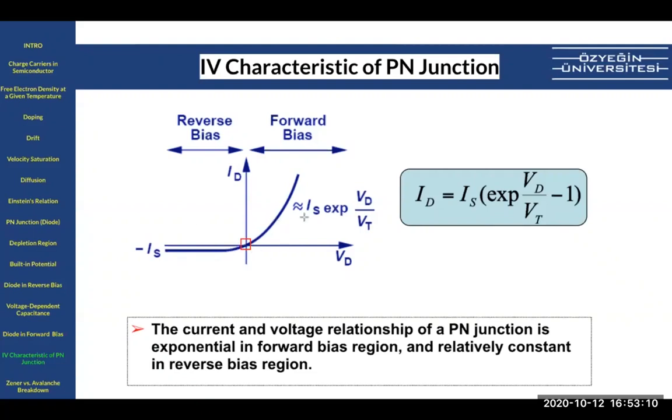But when we start to forward bias this junction, we make the diffusion mechanism much more important, and the depletion region gets smaller, right? Because the electric field in that region gets smaller, the diffusion currents start to flow, and now we see the current coming out.